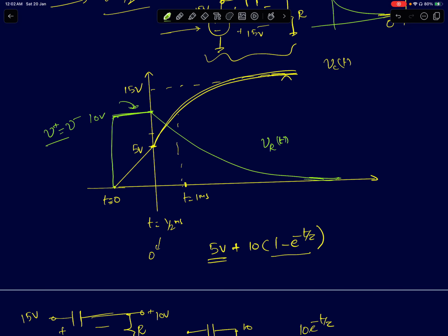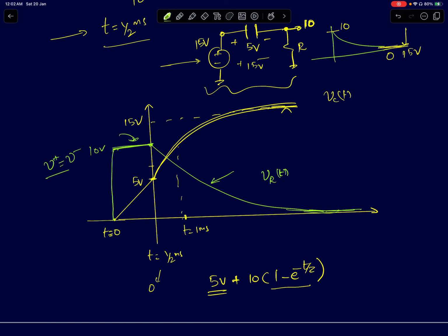After that, it goes through a first order discharging. Now the op-amp is completely inactive here. It's going through a traditional RC discharging. The op-amp is just providing the current that the circuit is demanding. I'm assuming even after it saturates, it provides that current. Now the voltage across the capacitor, on the other hand, started from 0 initially. It increased linearly to 5 volts. This is when the negative feedback was in action. After this, it's going to charge to 15 volts.